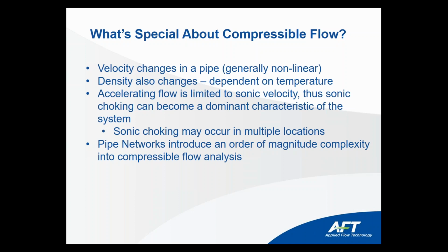So that does add a challenge to compressible flow analysis for the engineer undertaking that particular task. Additionally, gaseous flow can accelerate up to a point that we call the sonic velocity, and that leads to sonic choking when you achieve that sonic velocity. And sonic choking can very easily become a dominant characteristic of the system. Not only that, this is a little known fact, but sonic choking can occur in multiple locations throughout a piping network, in the same piping network as well. So that's an overlooked fact in industry and something to be aware of.